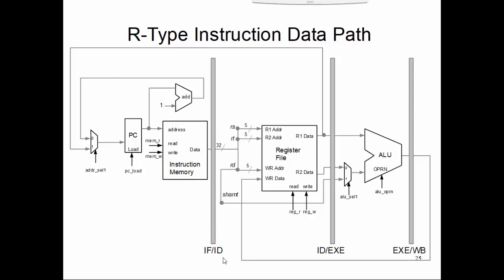each clock cycle, information from one instruction flows to the next stage, where the previous stage starts engaging in the next instruction. So let's say instruction 1, instruction fetch is done. That instruction information, the machine code and so on, will be transferred to the register fetch and instruction decode stage through the register, so that the input side of the register is now free to fetch the next instruction.